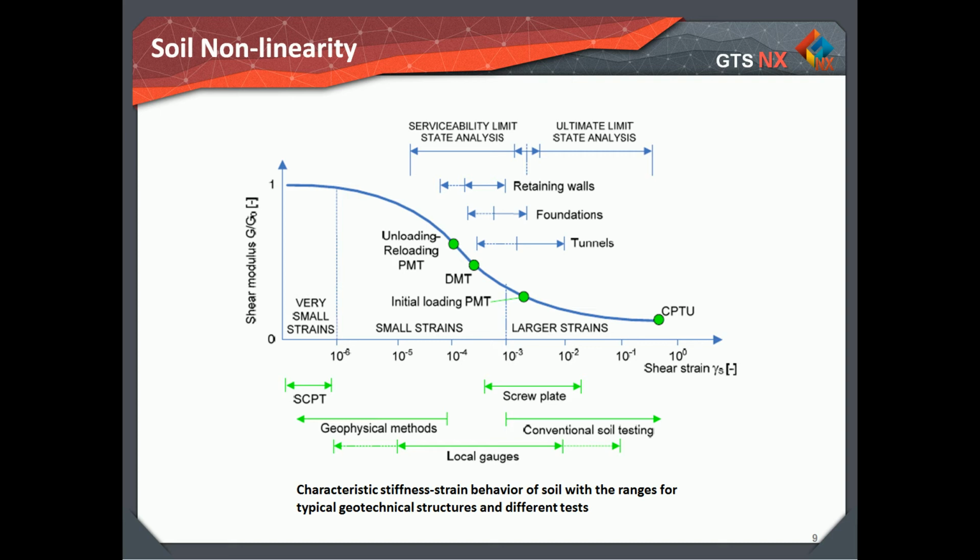Relevance of small strain stiffness: very stiff behavior at very small strains, vibrations, reduction of stiffness with increasing strain, restart after load reversal, high hysteresis in cyclic loading, energy dissipation or damping. Also relevant for applications like excavations, settlement trough behind the retaining wall, or tunnels, settlement trough above the tunnel.